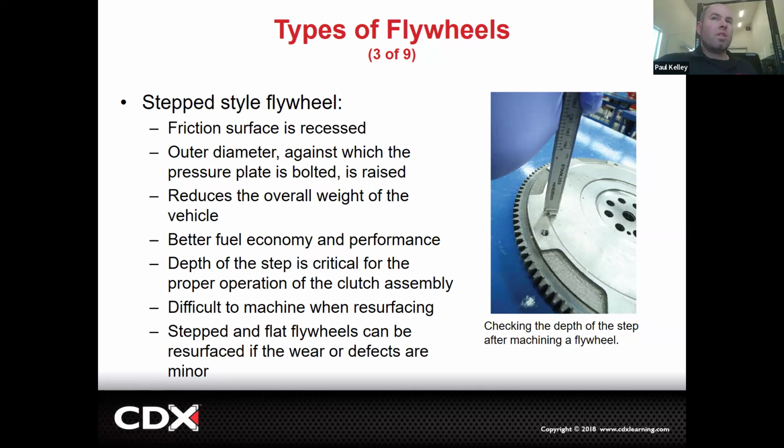So if you think about what I was saying with this, when I push the clutch pedal down, it's kind of hard to get it in first and it's hard to get it in reverse because it's still engaged because of the air in the line. It'd do the exact same thing if you mismachined this flywheel. But remember, they could mismachine the flywheel the other way. So if they over machine the friction surface, like we talked about first, but they under machine the step, that would mean it's going to actually slip.